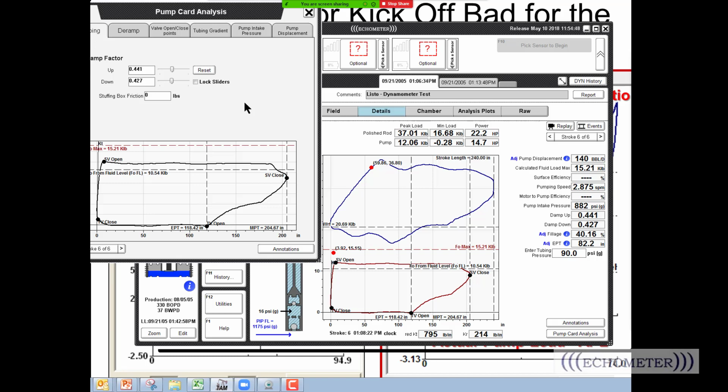And so that's just an example of running a pump below the kickoff point. You increase the friction, you increase your failure rate, you increase your operating cost. You can do it, but you have to pay. And that's just, now